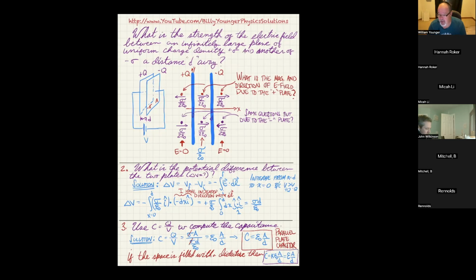One, remember we found that 3 million volts per meter, which is the strength of an electric field, will actually cause even air to be a conductor. So if you had an electric field as big as 3 million volts per meter between them, it would be a failed capacitor because the actual air separating the two plates would conduct electricity. So if you fill that air instead with some other insulator that can stand up to a larger electric field before failing, then you've prevented the capacitor from failing at even higher electric fields.